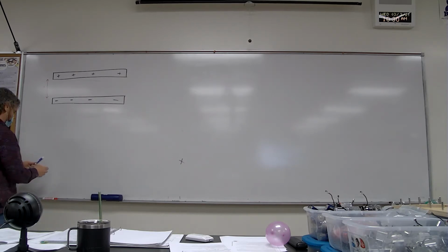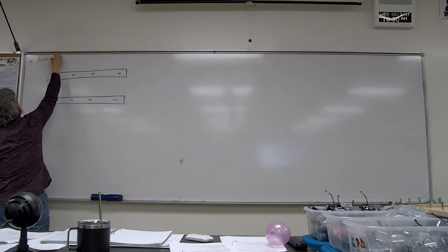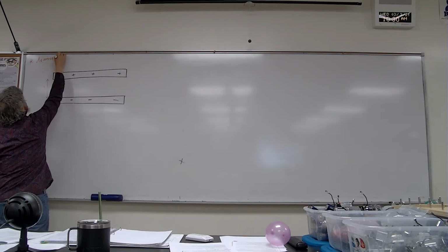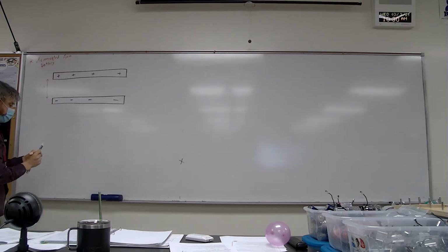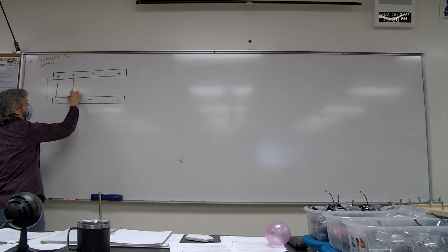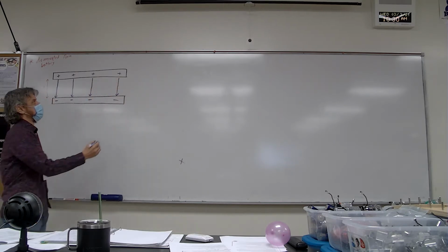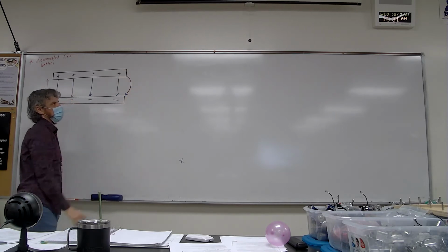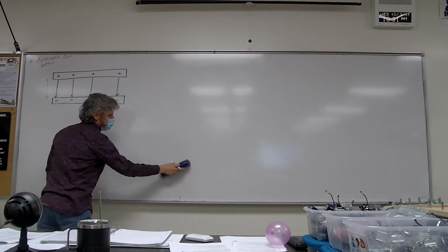Okay, so let me make a note there. Once it's charged, it is disconnected from battery. Once it's charged, I have obviously established an electric field pointing from the positive plate to the negative plate. Future electrical engineers in here, you do have to deal with what happens at the edges. You get what are called edge effects, but essentially it just kind of does that. But you do have to take that into account when you're dealing with very sensitive electronics.